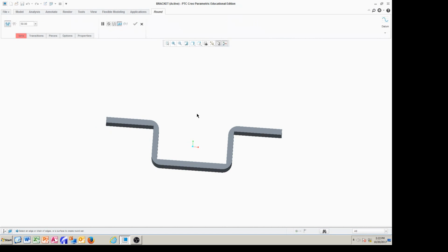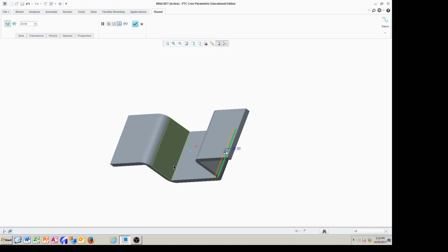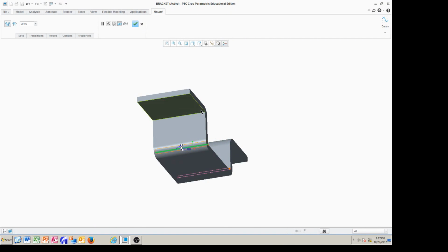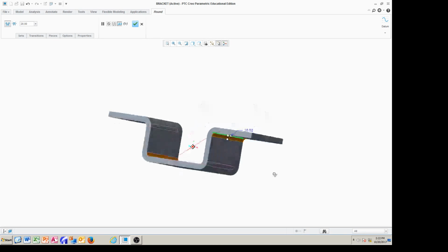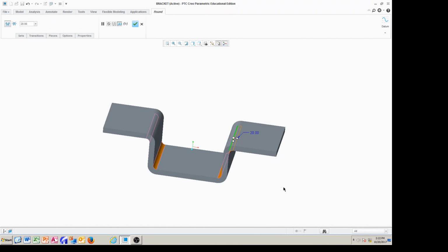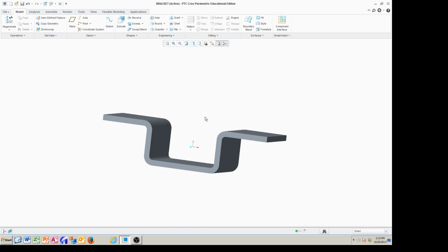So we go to round, and I'm going to click on inside here, and that is not 15. It's a 20. Okay, and the round for the interior portion we call 20, and we repeat that in here. And then I need to do the same thing underneath here. There, so it will keep that strength, because the material has to be reinforced by means of fillets and rounds, so that we have this nicely secure, and we want to ensure that it doesn't break.